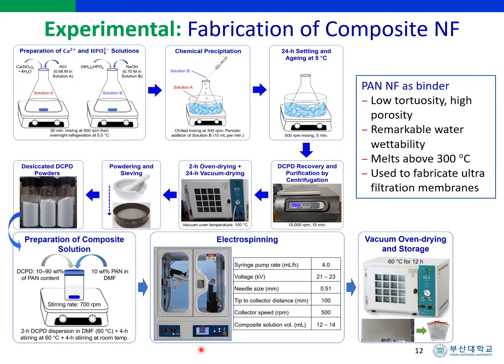The electrospun mesh of nanofibers was collected, covered with aluminum foil, vacuum dried at 60 degrees Celsius for 12 hours, and then stored in a moisture-free plastic zip bag. The mesh was then cut into pieces of desired shapes and dimensions, and peeled from the aluminum foil before its use in further experiments.